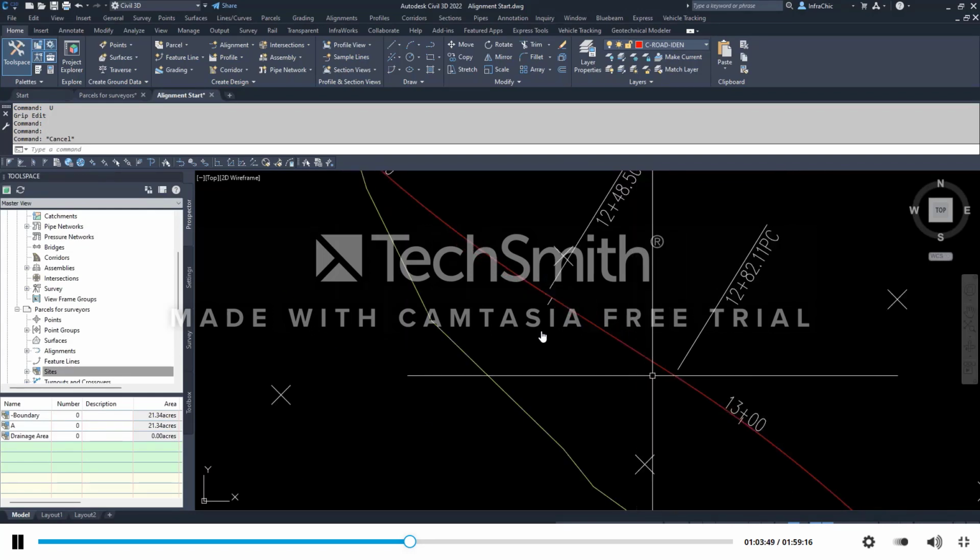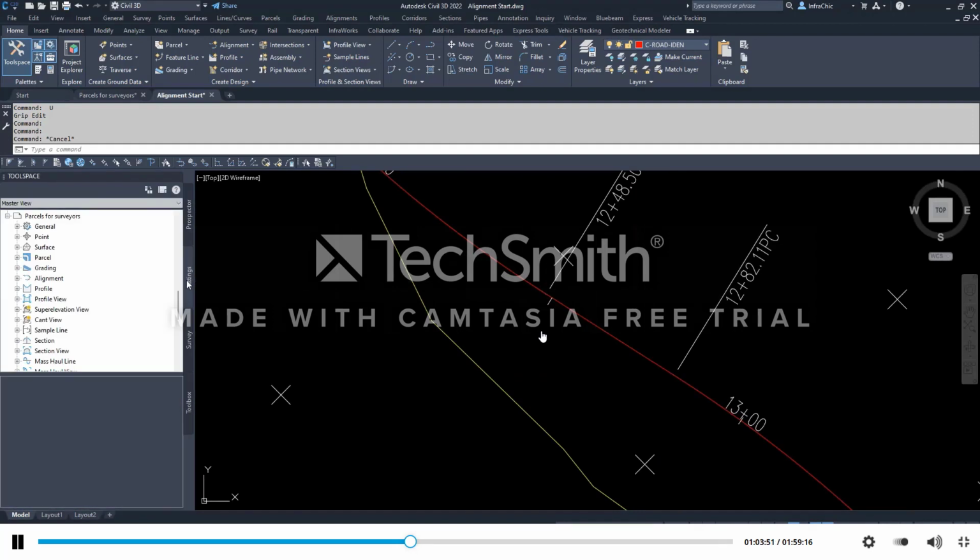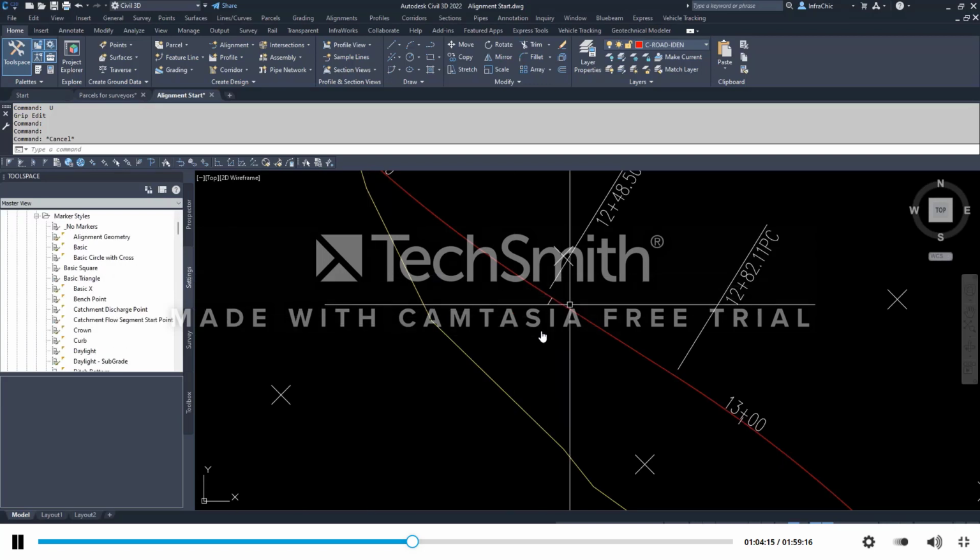It is the same marker, and it is sharing the same object style as used in points. Is it points? That's wrong. Sorry, markers in general. On the settings tab of the tool space, under general, multi-purpose marker styles, these markers are here, and they are shared in corridors, in alignments, and profiles.